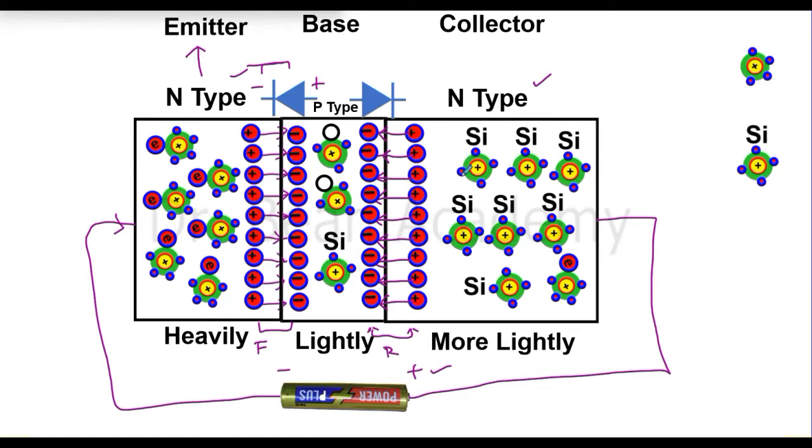When we consider this junction, just see the image. Now the collector n-type is connected with the positive terminal, and here we can see that this p-type is connected with this side, although the negative is connected with the emitter n-type, but this is connected with the p-type as well. And if you see the symbol of the PN junction diode, we can say this one is connected with negative and this one is connected with positive. So this junction is in reverse bias mode.